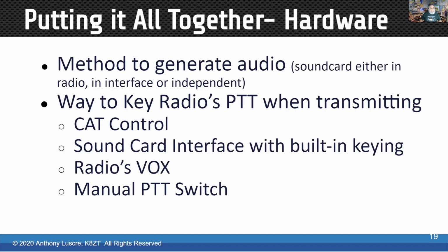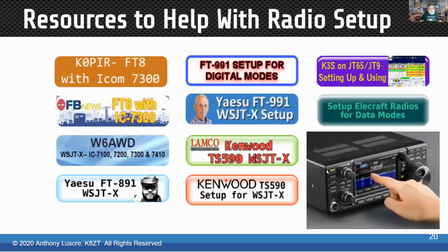And then you also need to have some way to synchronize your time, and most people will need to install a special program if you're running a Windows machine, because the Windows time syncer is not sufficient. You also need a method to generate audio, either the sound card in the radio, a sound card interface, or an independent sound card, and then a way to key the radio's push to talk, usually CAT control, but you can also do it with the sound card interfaces, which have built-in keying, or you can use the radio's VOX.